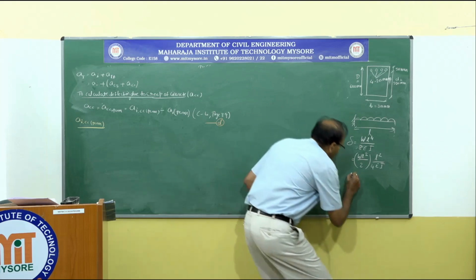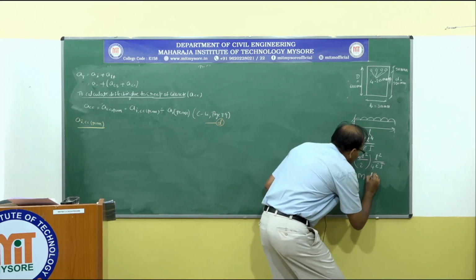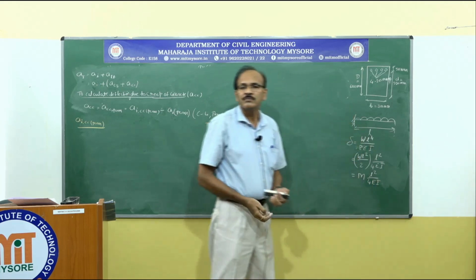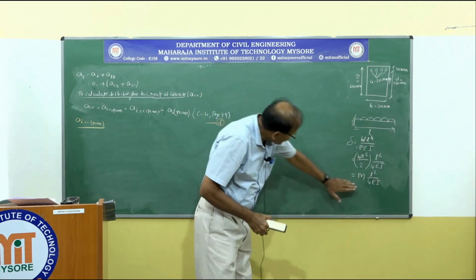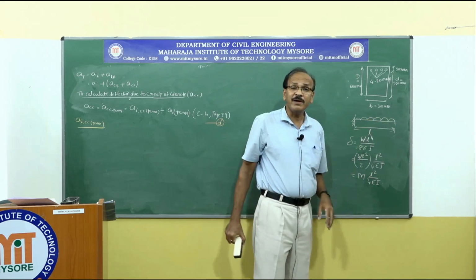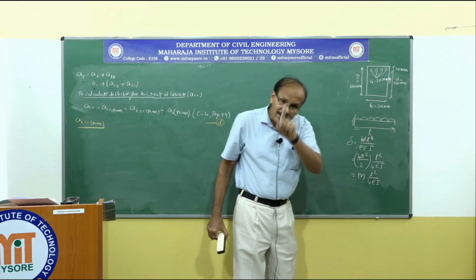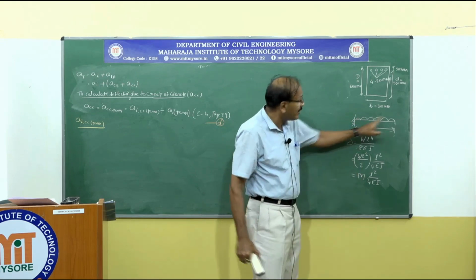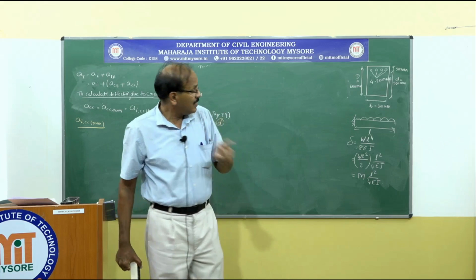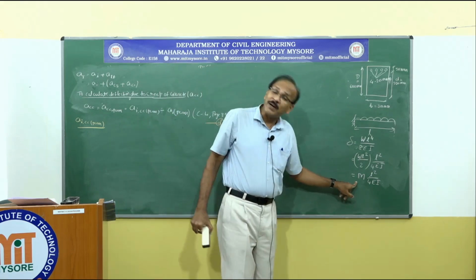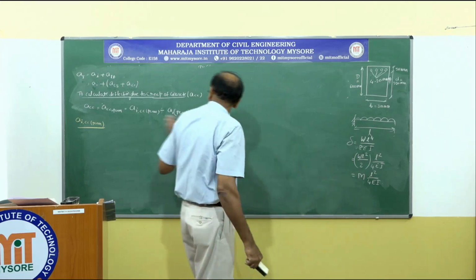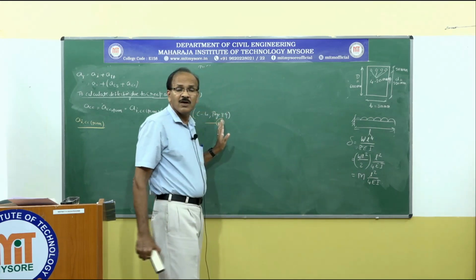So that is M L square by 4 EI. Then what is M? Yes, that is a maximum bending moment. So what is the maximum bending moment? Here we should not consider the total service load, instead we should consider the total service permanent load to find out these two deflections.